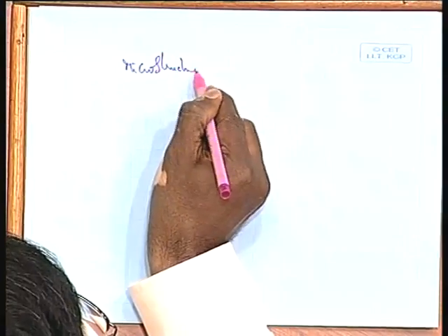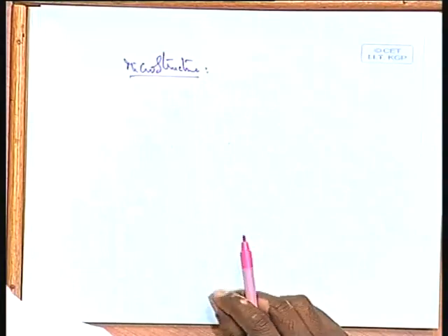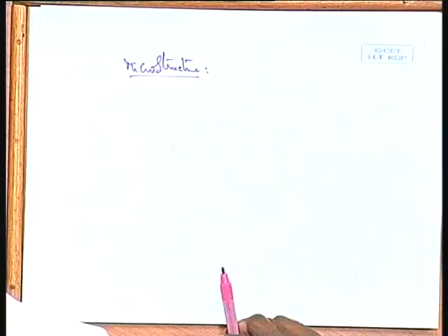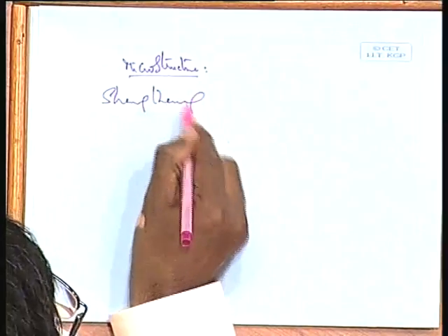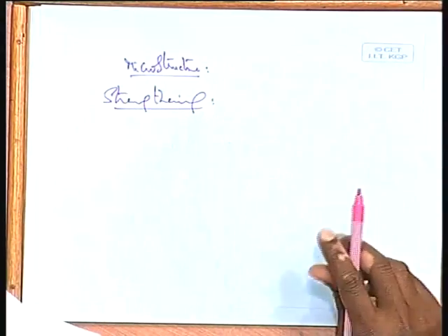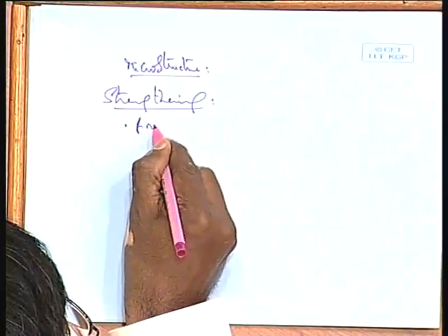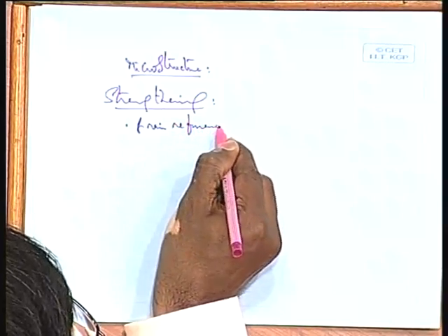Before we really go into various advanced materials, we need to understand how a microstructure plays a very important role. To understand this, we need to understand what are called the strengthening mechanisms. All of you at your undergraduate level must have heard to some extent about the strengthening mechanisms. For example, if I take a pure metal, let us say aluminum, how do I make it strong? What are the ways by which I can make it strong? Grain refinement, fine, that is one. Anything else that you can think of?